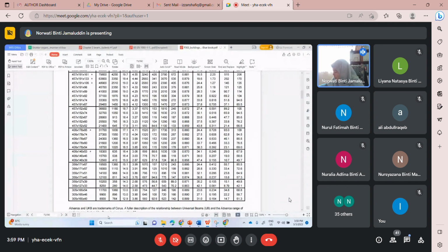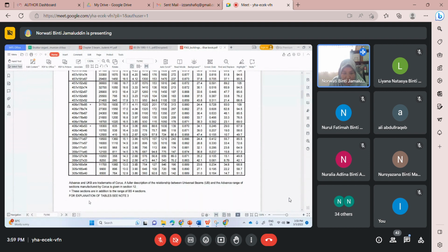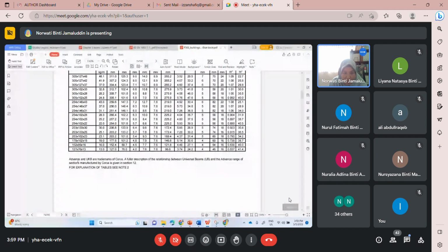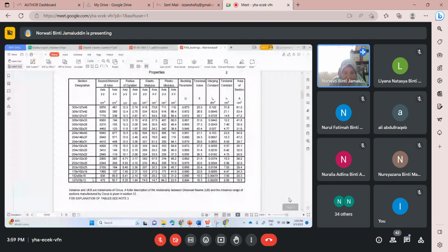If you convert 66.1 to centimeter, you get 6,610 centimeter to the power of 4. That's why you need to choose slightly more. Let's try another size. This one is not fulfilled. What about this one? No, not fulfilled. I required is 6,610. Oh, you can choose 700.